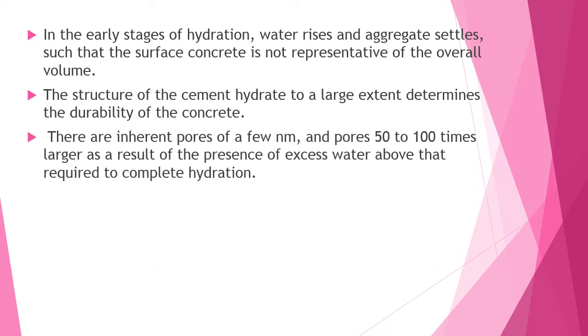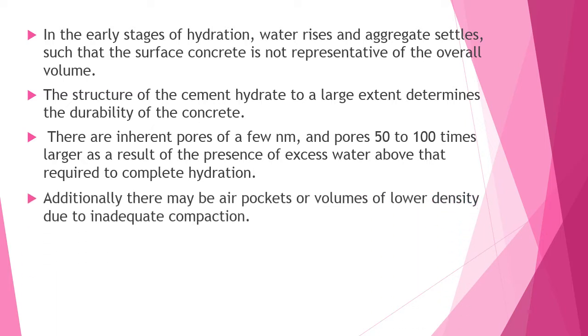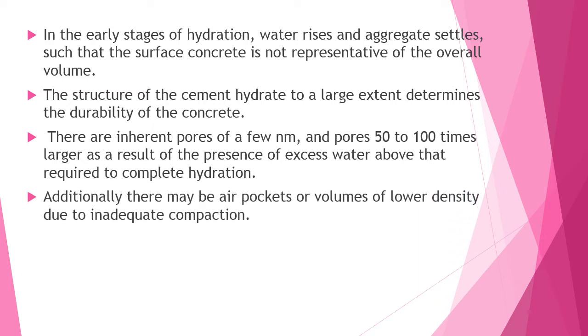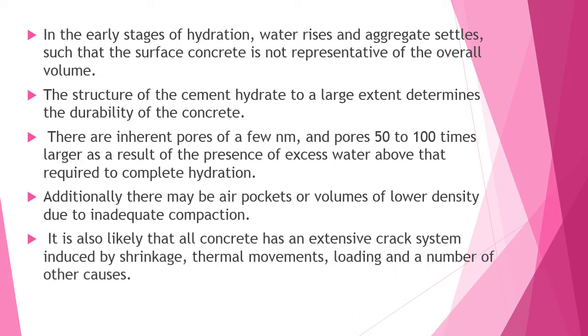There are inherent pores in the nanometer range and pores 50 to 100 times larger as a result of the presence of excess water above that required to complete the hydration. Additionally, there may be air pockets or volumes of lower density due to inadequate compaction. It is also likely that all concrete has an extensive crack system induced by shrinkage, thermal movements, loading and a number of other causes.